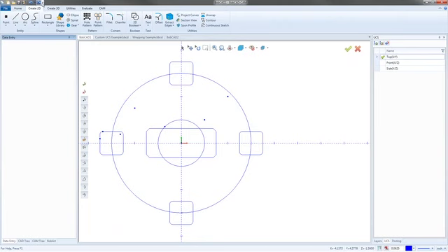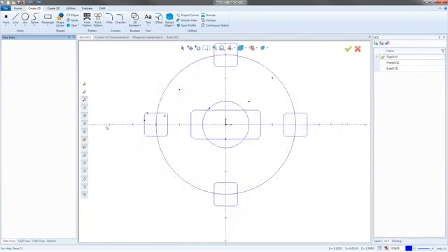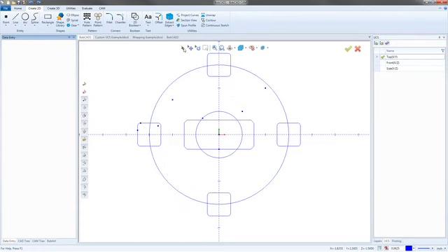Not too often do I even use that one, but the times that I have gotten the chance to use it, it's been a great function. Little things like moving a part straight over, but not knowing the distance. I could snap a point on the part, a known location. I can then use the point perpendicular to create another known location a certain distance away without me having to know the distance. And then I can take a measurement and translate parts. It really depends. It's probably one of the least used functions out of there, but it is a very cool function.